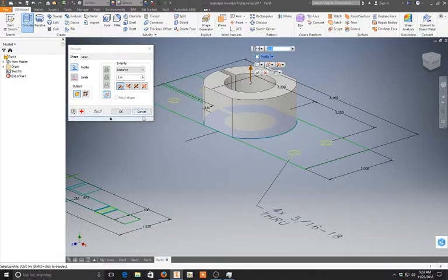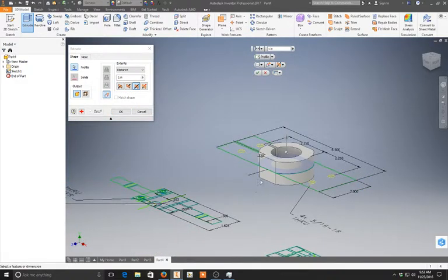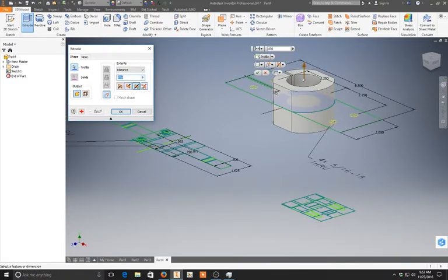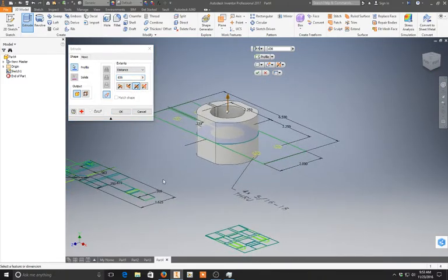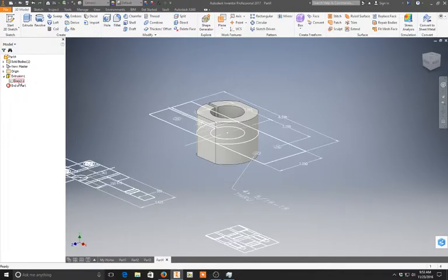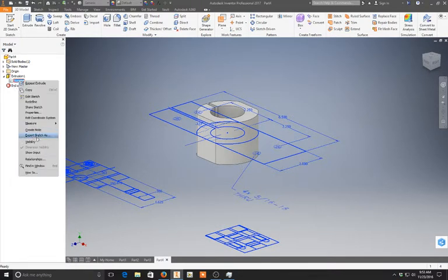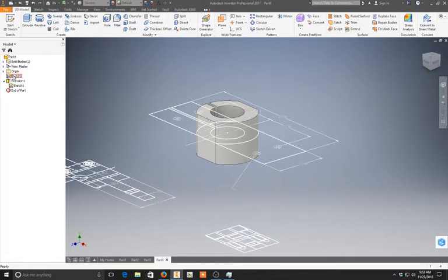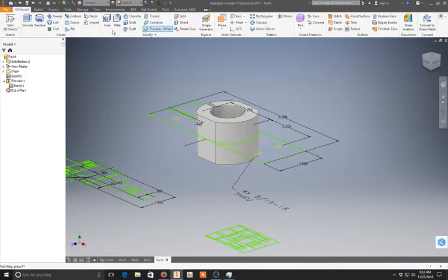We can click on all the geometries. I clicked on the middle geometry there, turn it to symmetrical. The distance I'm going to use is this distance right here, so I just click right there. It says D36 because this is dimension 36. That's just the name it gave to it, and say OK. Then we're good there. So whenever you extrude a sketch, it's going to consume the sketch. So if we want to use it again, we have to either right-click on the sketch and say share sketch, or we can just drag it up like that, and it'll do the exact same thing either way.